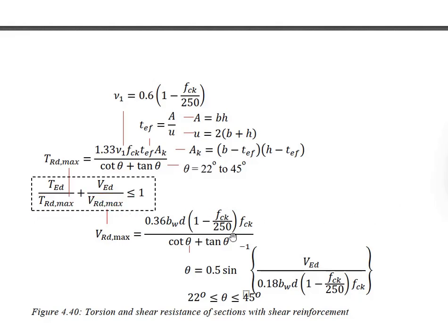Very often, if you change the geometrical properties of the section, the geometrical property of the other part will also be changed. Therefore, while doing the calculations, if you have revised the sections, make sure you recalculate all the geometrical properties. The shear design here is meant for the entire section, whereas the torsional design here would be referring to an equivalent box section. Alternatively, you may modify the concrete strength.